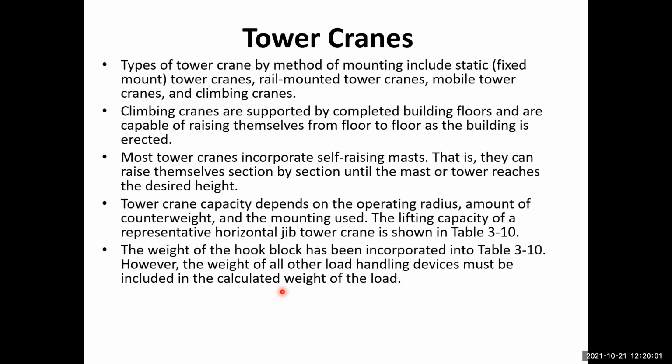So as an example, in table 3-10, the weight of the hook with which the loads are attached is incorporated into the values provided by this table. However, the other weights, the handling devices, must be included in the calculated weight of the load.